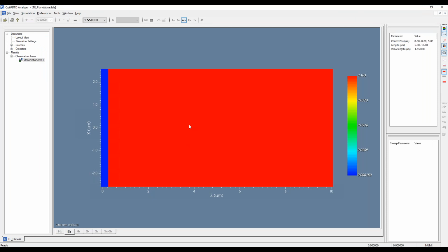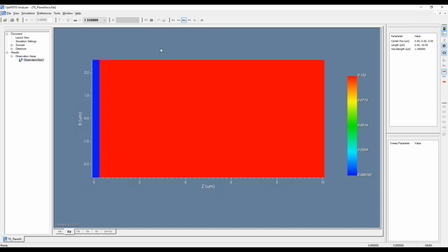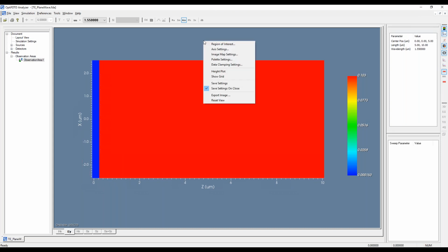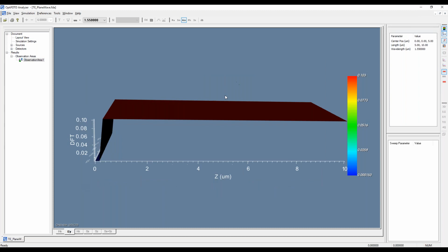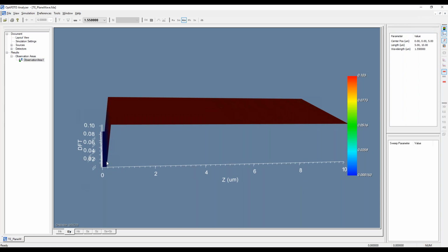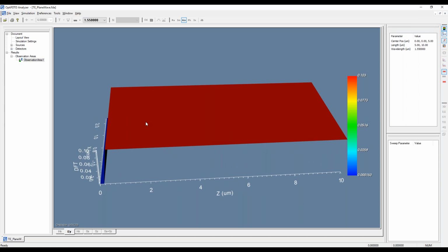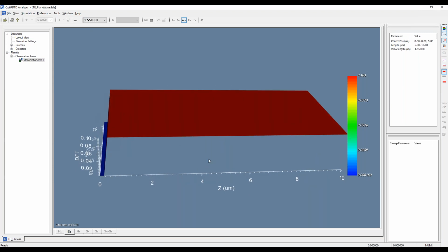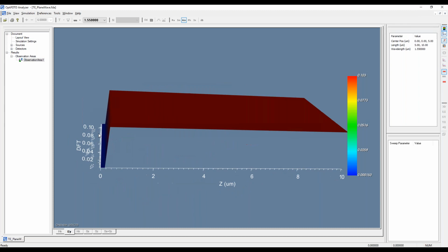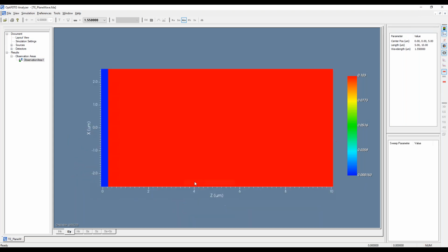Right? So maybe this is not what you were going to expect. It's a very, you could say, boring type of plot. Trying to right-click here. Okay. Right? So over here, I had set my input plane, so that's why behind it, it's kind of close to 0. But this is the observation area, what's detected at this frequency, 1.55. So this is the z-coordinate, and this is the x-coordinate, and this is the DFT value, the complex field value. And now let's investigate this and see if what we said about plane waves is true.